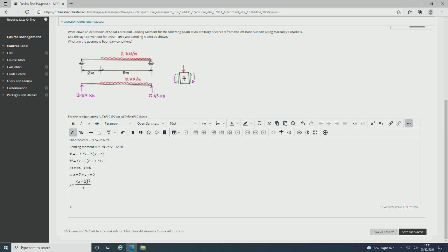Similarly, if you have got a rectangular section and a diamond section of the same area, then the rectangle has got higher I, because in the diamond more material is towards the center, for example. So some multiple choice questions along those lines would be there. Is there anything else regarding the test? Yeah?